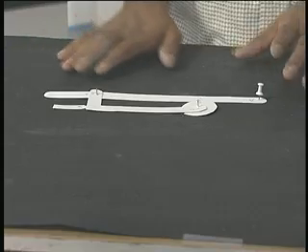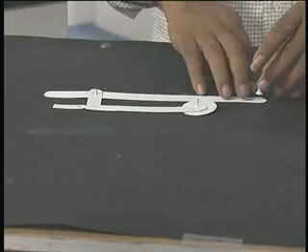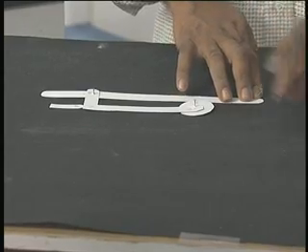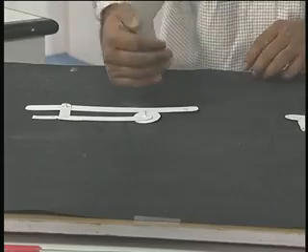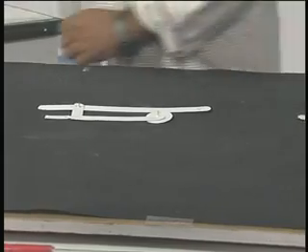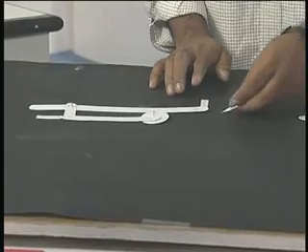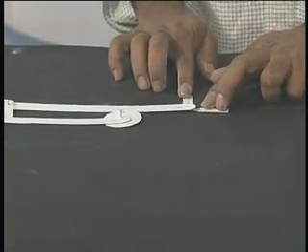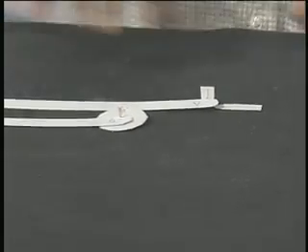In order to make this body free from the fixed frame, I need to remove A. What does A do? It does not allow the point A to move either in vertical or in horizontal direction. So I am going to insert the two restraints Ax and Ay. Now this is a free body that you have for the entire system.